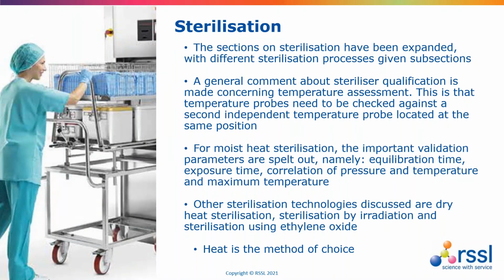With sterilisation technology, there's expanded text about the importance of temperature control and testing that thoroughly during qualification, and advice on the numbers of temperature probes and for verification of temperature probes. And there is tighter guidance on freeze drying, on the control of lyophilizers, and how they need to be sterilized before each load, and tighter requirements around those freeze dryers that are still manually loaded.